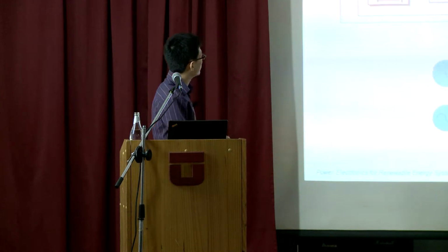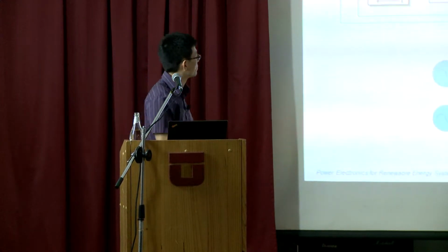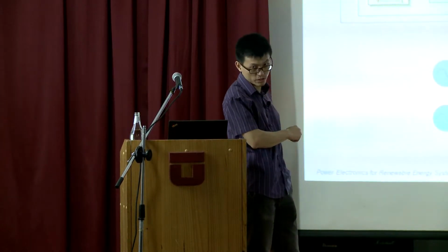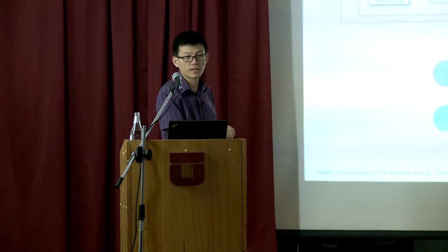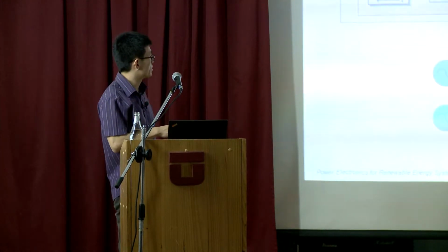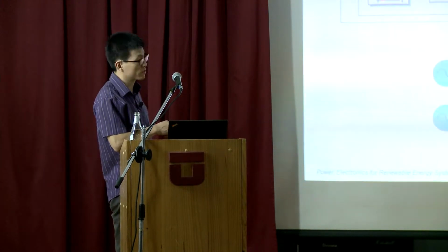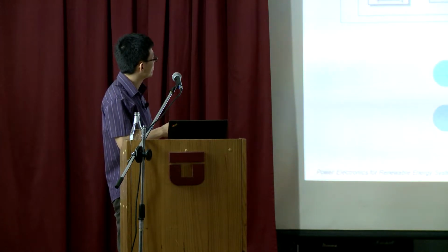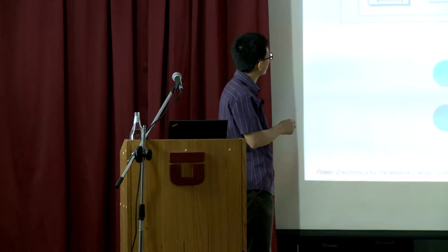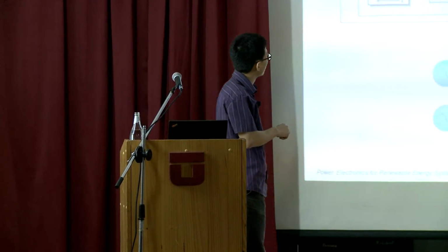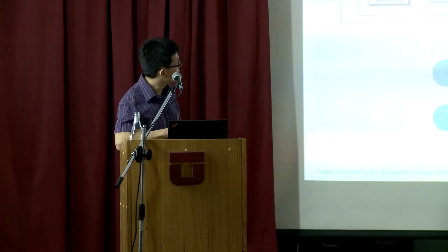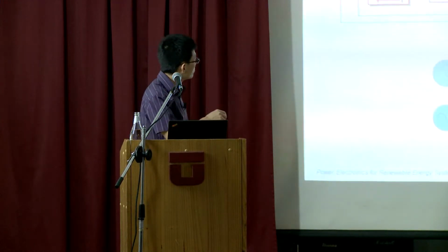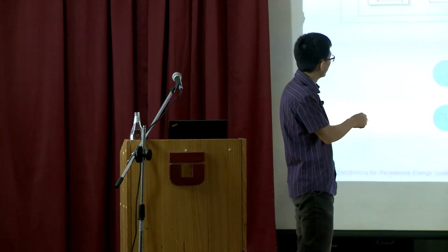So you have one system, and you have multiple systems. What you really have are multiple generator systems like this. Every local current is fed back to its own droop controller. This is the concept. You have the multiple generator system, and then you feed back all the local currents to your droop block this way. And you have a different voltage reference supplied, and afterwards this control loop gives you V1, V2 or V3, because this system has only 3 generators.